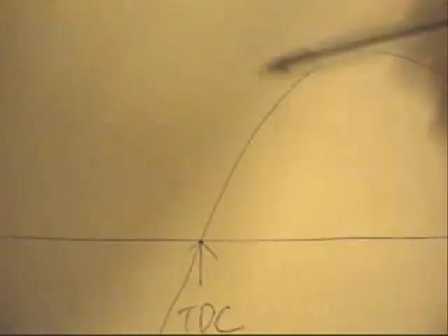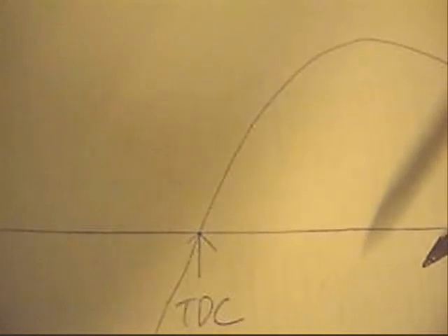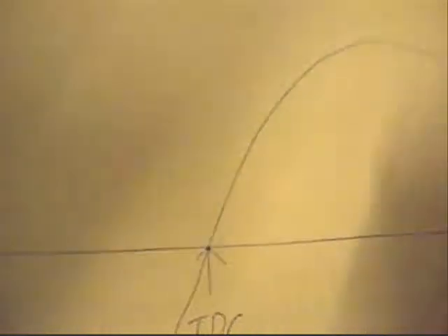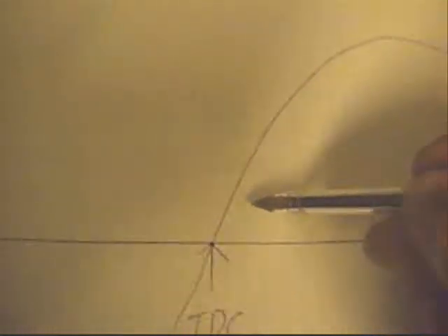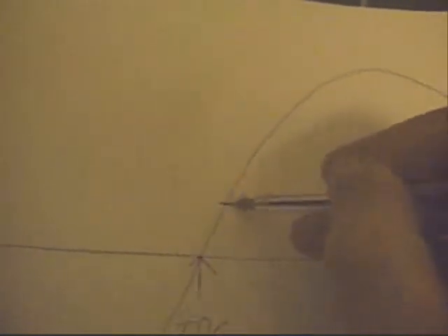Got voltage going up. Now on the transistor, you've got a minimum voltage where the transistor begins to open, and the saturation voltage, which is the point where the transistor is fully open. So for example, on this sine wave, we'll assume the minimum voltage is about there and the saturation voltage is there.